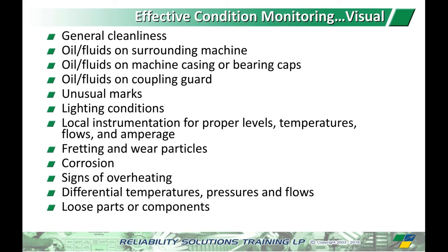Talking to one of our fluid power instructors the other day, an old school way that I used to do when I was growing up, looking for very small leaks on fluid power, is we take toilet tissue and wrap it around the fitting, and the osmosis of the tissue would actually draw any oil out. So even very, very small low-grade leaks we were able to identify.